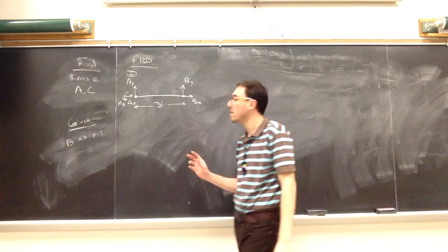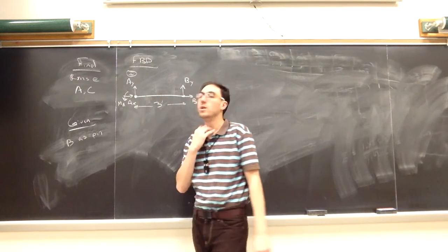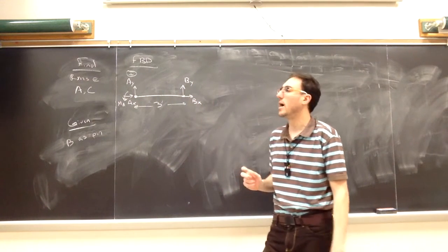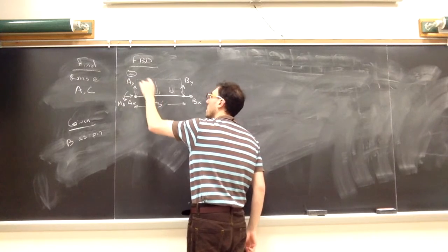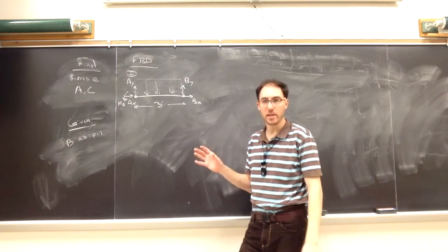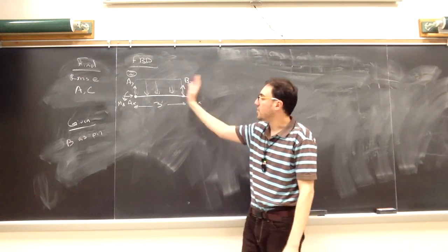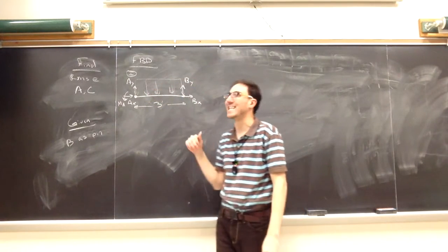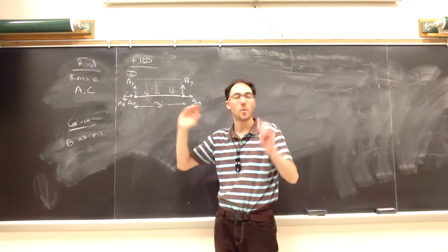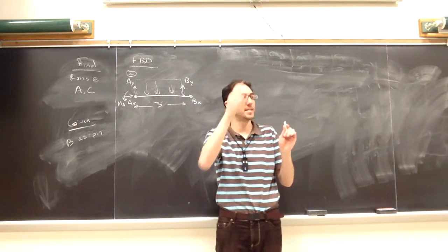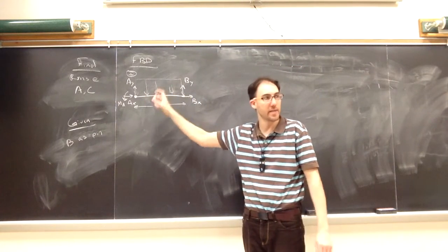I have to account for that distributed load that's acting on just the section that goes from A to B. If we look at the picture, that section of the distributed load, I'll draw it kind of faintly here. We're only looking at the part of the load that touches A to B. We don't care about anything from B to C for this picture. It's a distributed load, and across the entire height of it, the intensity is 500 pounds per foot. When we break it down into the sub-pictures, we have to look at only the load that's acting on that sub-picture when we simplify it. So that's the right idea, but we have to be careful when we're looking at the individual members.